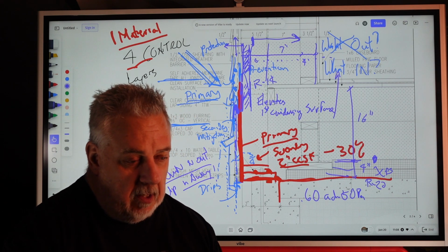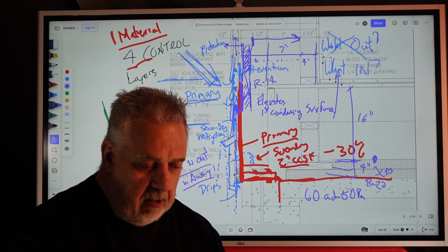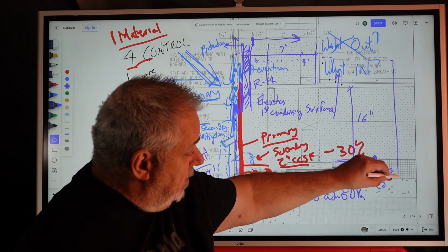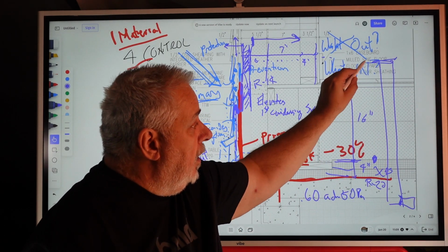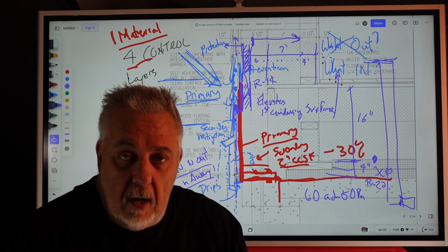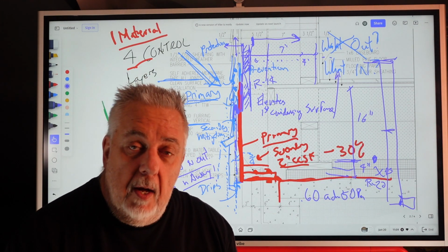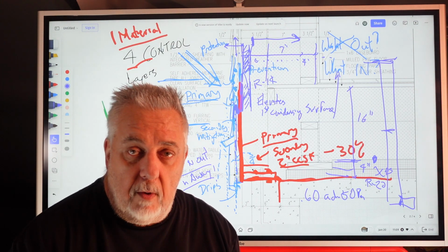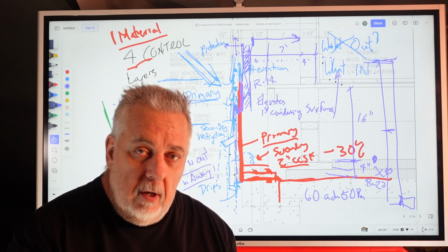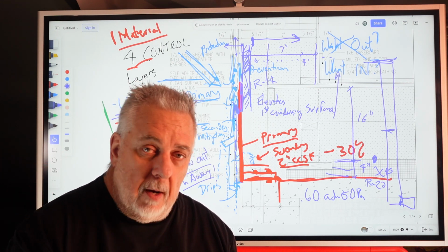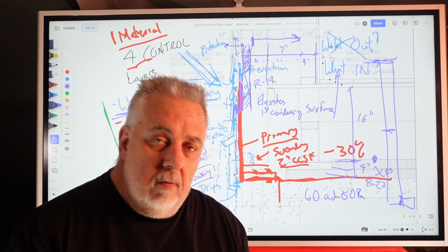almost crazily specific about. Pipes went all the way from upstairs through this space, so there are no joints. The joints are down here or up here. Those were always solid pipes going through the system, so we never wanted to put a joint in any of the plumbing pipes there, because if the joint failed, then we would have a major problem. So we're going to make sure all water, up or down, bypassed. And actually the up water was coming in from above, so only drain water basically goes through that system, and it goes through a continuous pipe.